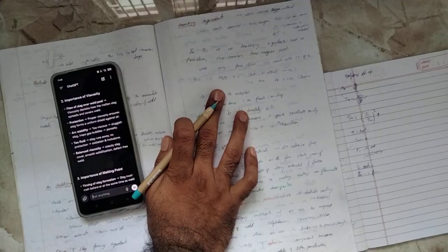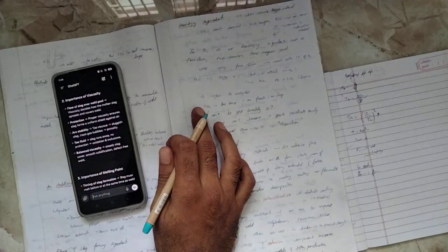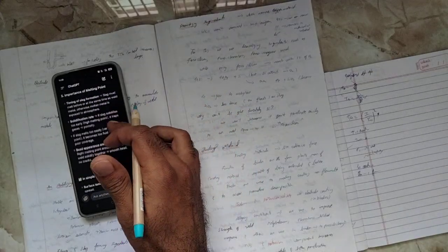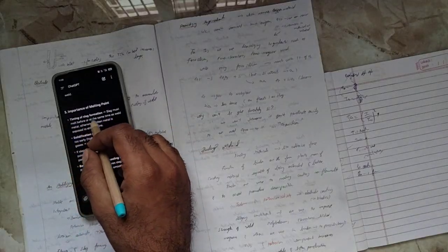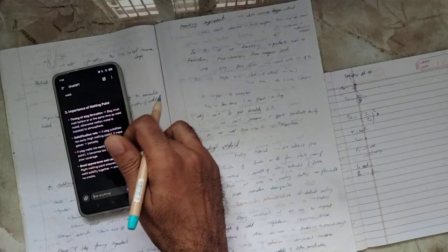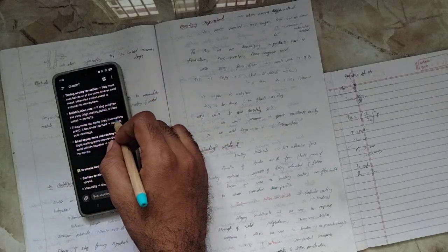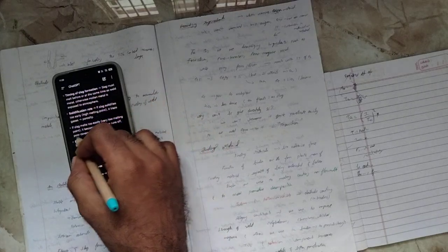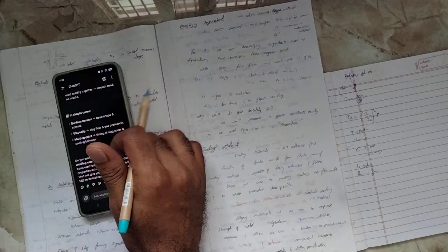Next, if the slag is less viscous, that is also a problem; we just need balanced viscosity. An important property is the melting point, because of the timing of slag production, because slag must melt before the weld metal. If the slag doesn't melt, it also complicates things. If slag melts too easily, at a very low melting point, it becomes too fluid and runs off. So that's why each and everything is so important.